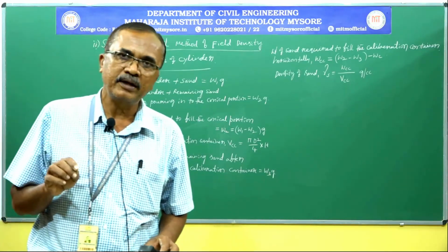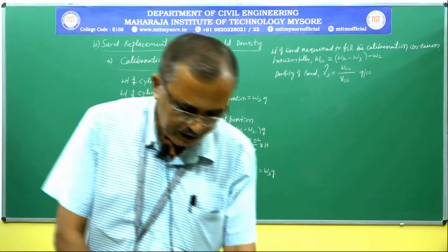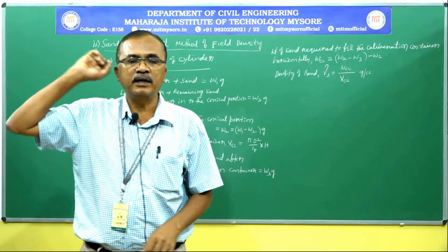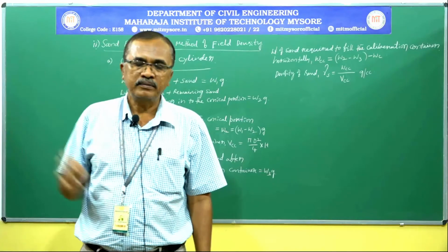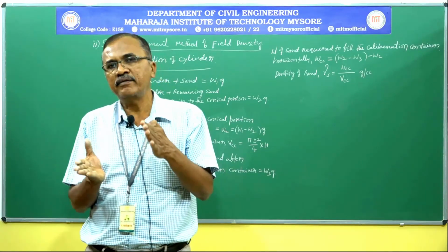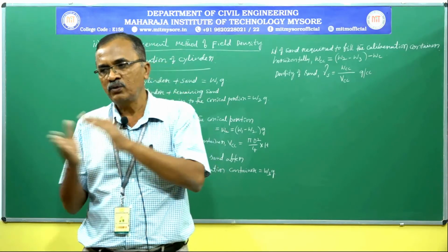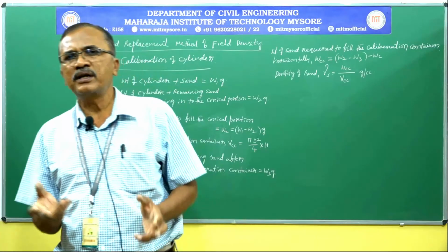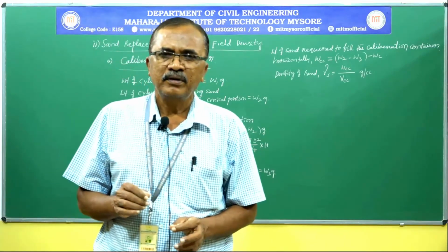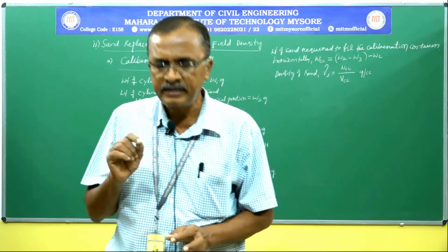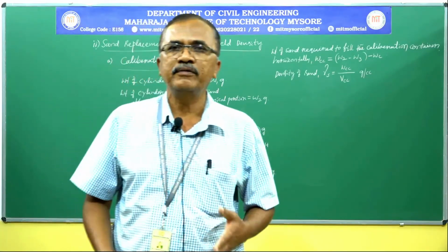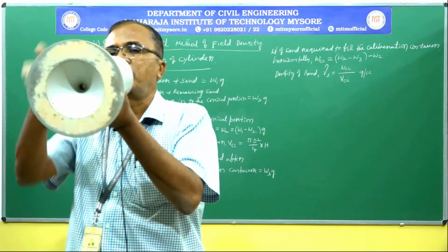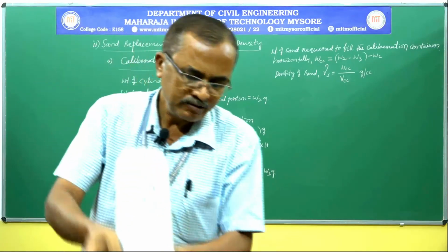600 micron or 300 micron sieve. So, we know the particle size range; it ranges from 80 millimeter to even smaller than 1 micron. So, the small range of sand we use, 1 millimeter to 600 micron or 300, is a small range, meaning it resembles uniform size of particles. When uniform size particles of sand are used, the sand will easily slide over each other and it can easily flow through this small hole. Through this hole sand can easily flow.